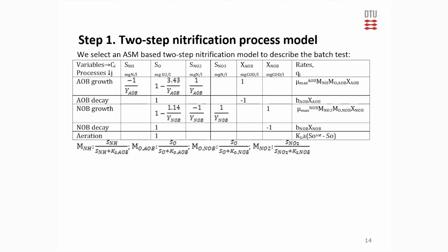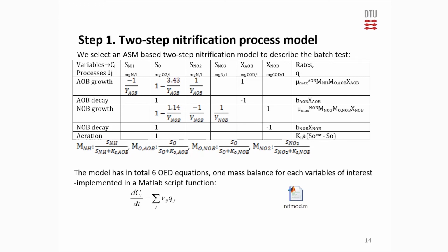Since this is a batch process, input and output mass flows are 0. Hence, the mass balance equation is simplified to simple conversion terms. 6 ODE equations represent the system dynamics as a function of time. These are implemented in MATLAB as a script function.